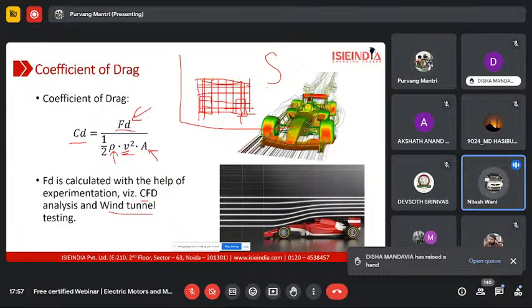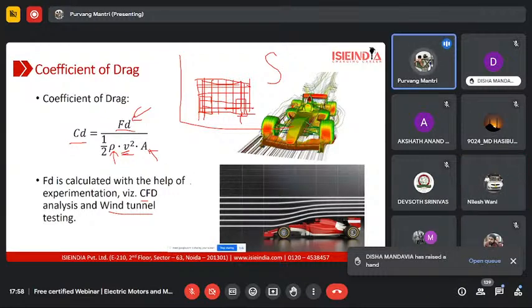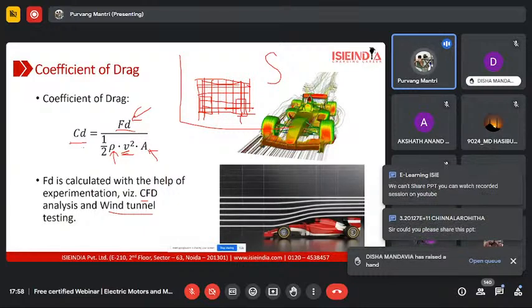In the bottom here, the red car. If I calculate the frontal area, I will get the same. But if the curvature is very smooth. So in those cases as well, you need to go with the same method, because industry experts actually use the same method, but they mostly rely on CFD analysis. They might calculate the frontal area by this method, by projecting the frontal view on a plane, because they want to calculate the coefficient of drag. But most of it can be acquired from CFD analysis and wind tunnel testing.